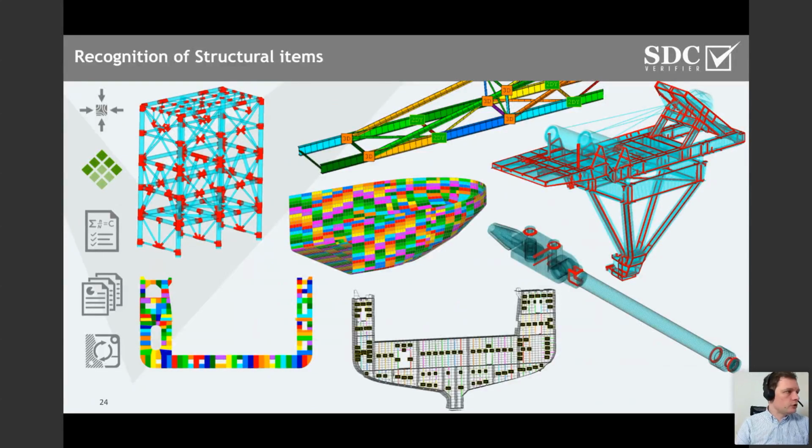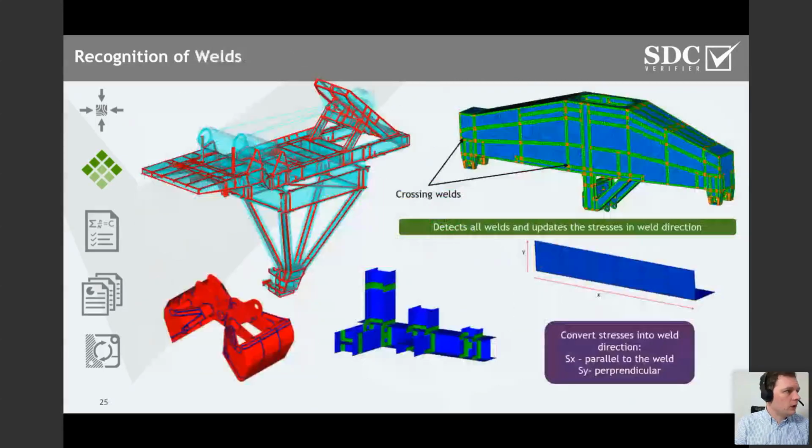And how to do that, I will show an example of only one member. Most common is to identify welds within our software. So the software defines weld lines based on mesh connectivity. So any kind of material change, property change, thickness change, connection of a certain angle, or a contact on both 2D and 3D elements, so shells and solids, is automatically identified as a weld line.